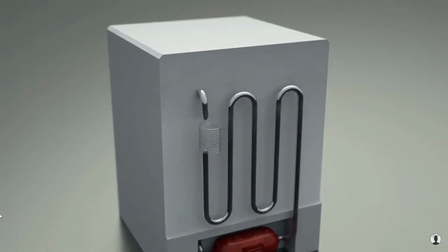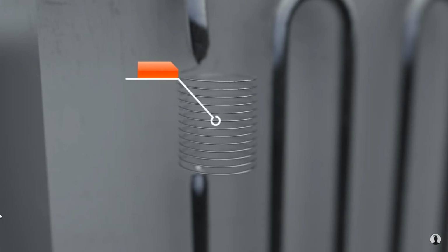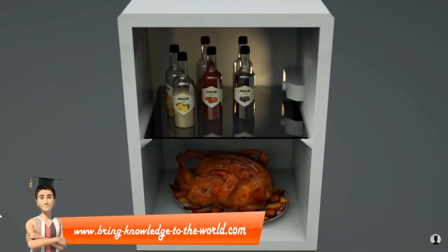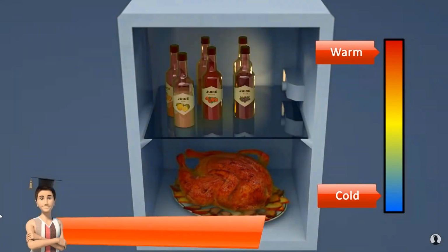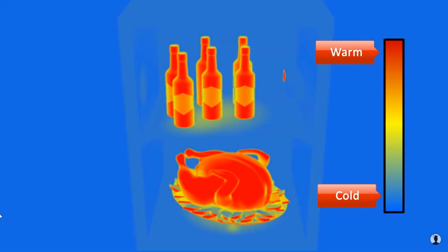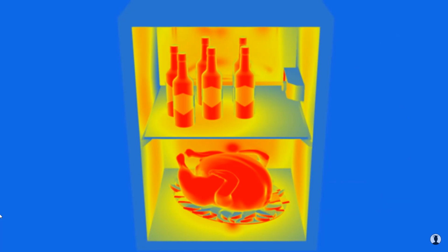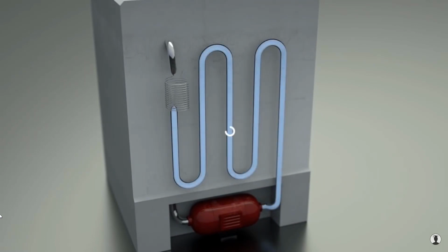Evaporator and condenser are connected to each other through a throttling device, such as a tube with a very small diameter. Normally, food placed into the fridge has a temperature above 10 degrees Celsius, and that's exactly where the fridge gets warm. So this heat has to be transferred back into the environment. Heat transfer into the environment is done by the refrigerant such as isobutane.